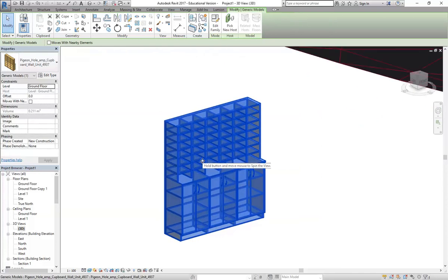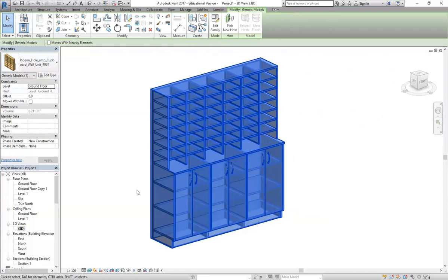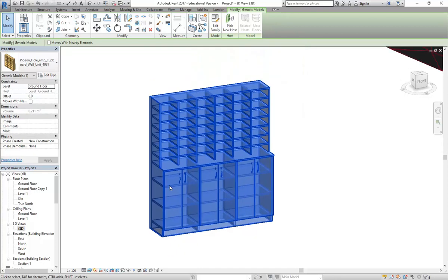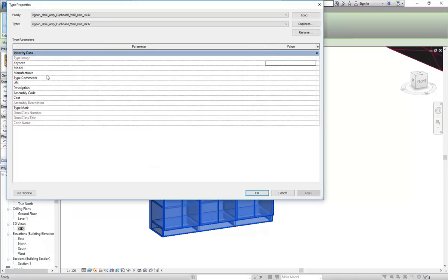Okay, so this is exactly what I was talking about, and what you were suggesting maybe happens when you download things even from Revit City that are in the right format. You then can't change the materials. So here, how do we change the material? What would you be trying? Select it, maybe. Have a look at edit type. That'd be the first step. That's what I'll be doing.